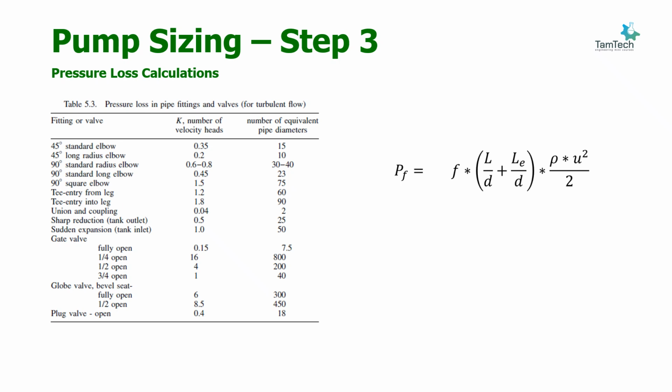If it's interesting to you, you can put a comment below and we will share a video related to our major and minor loss methods. But all in all, we can use here friction factor multiplied by length of the pipe divided by diameter, which represents major losses, and this term represents minor losses: LE divided by D, which is found from a chart or table, and the summation of them.